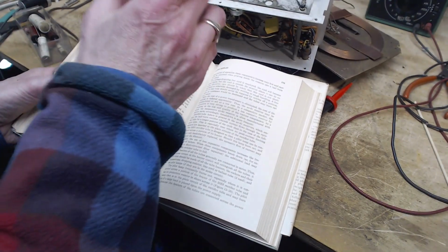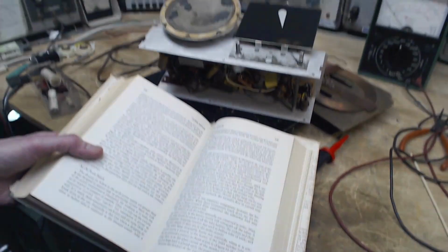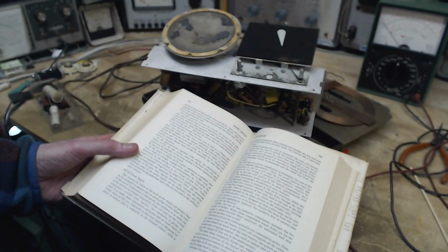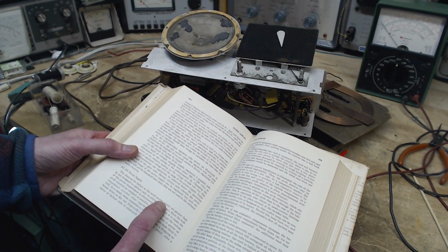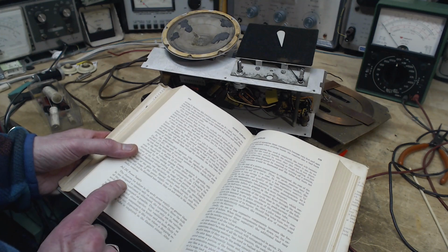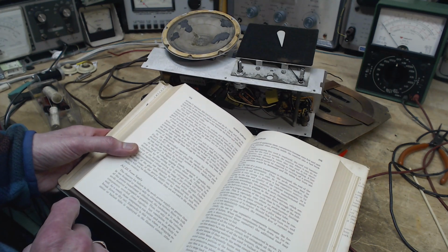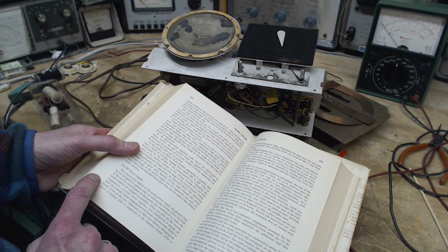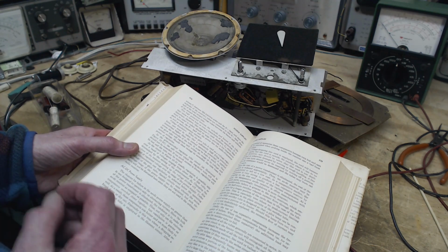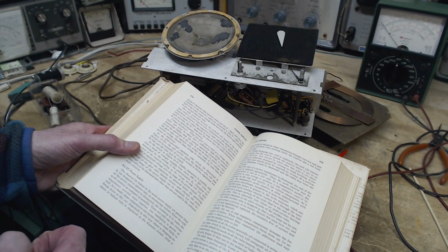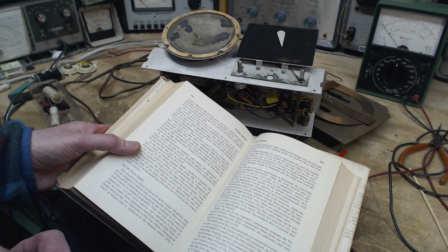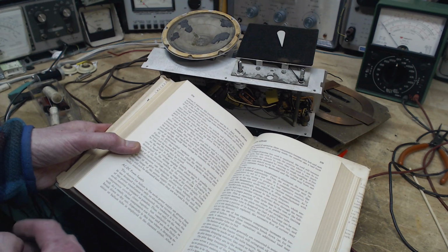AC/DC power supply. So this is an AC/DC radio. Up here you could plug it into a DC power, but nobody has that. This is interesting though. The chances of failure in the AC/DC power supply are greater than in one designed to operate only on alternating current. Since the bulk of the power transformer is eliminated, the tendency is to make the AC/DC receiver as compact as possible. Thus, not only are the various components crowded closer together, but ventilation is poorer as well, and as a result, these components run hotter and are more likely to break down or dry out.